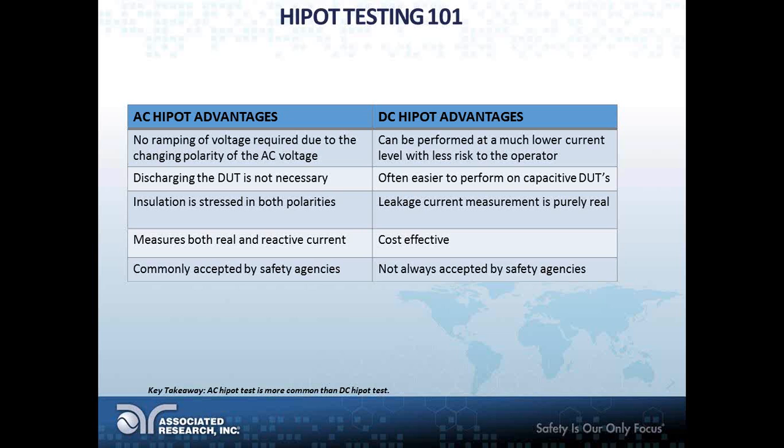Today, as we know, many products have higher capacitive leakage currents because filter capacitors have been added to the input circuits to enable them to comply with agency regulations. And also, the resistive leakage current within a product is primarily dependent on the type of insulating material that was chosen for that product, and also the applied voltage. The exact value of the resistive leakage, or the real current, is usually the determining factor that dictates the quality of the insulation at a particular voltage.